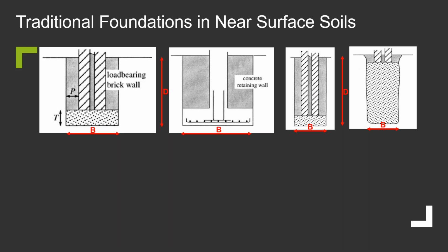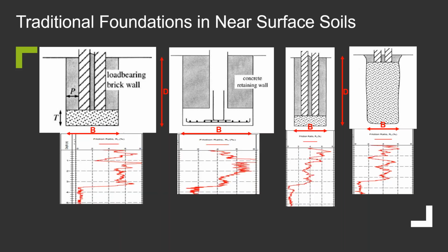for the purpose. What we'll be doing throughout this exercise is looking at the depth into the ground the foundation needs to go and how wide it needs to be, or what its breadth is, so breadth B. And we'll be using our interpretation of the ground profile below certain depths in the ground to determine at which economic depth we should place this foundation. And then we'll come up with options and we'll cost them.